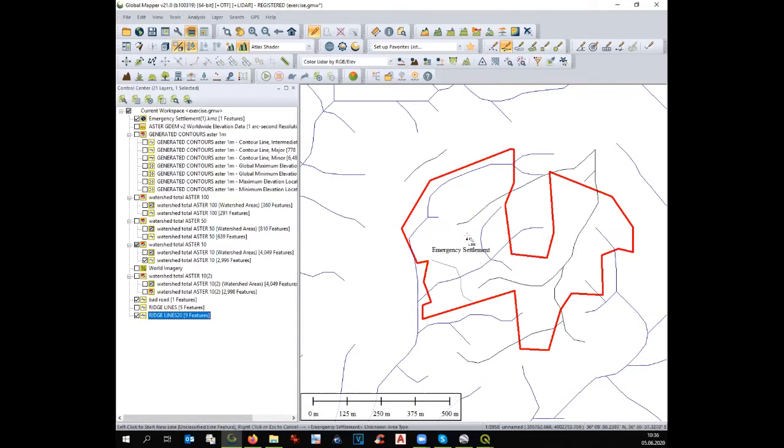You get it? So this is the road that we plan. When it rains, water goes into the drain automatically on this side. So this road doesn't need any culvert. This road doesn't need any protection because on the left it goes down, and on the right it goes down. You get it? And then the natural stream will be here.